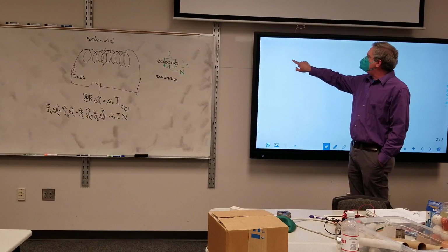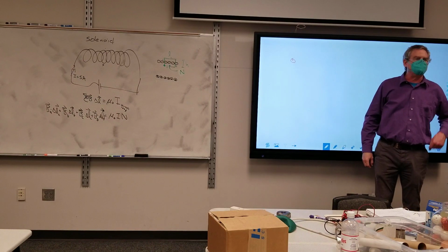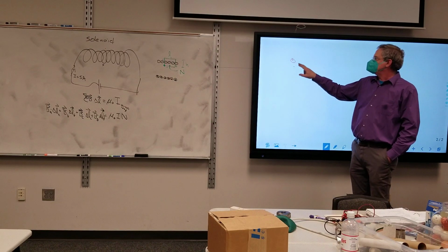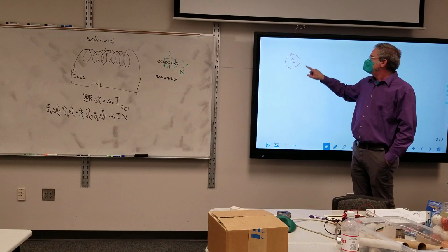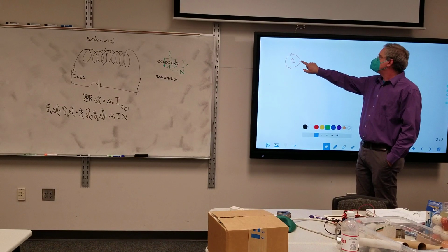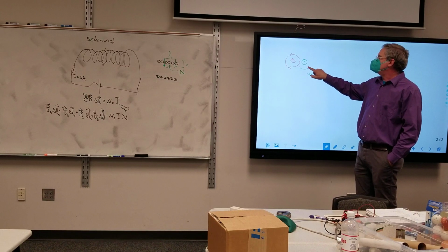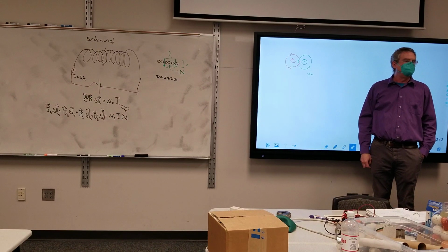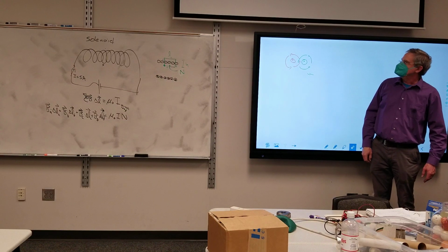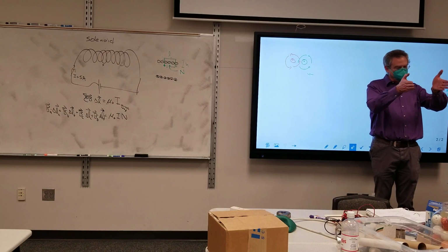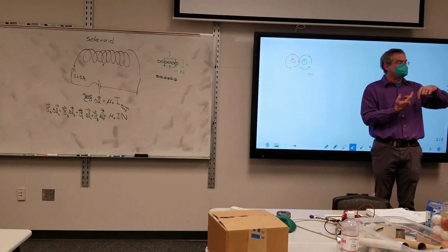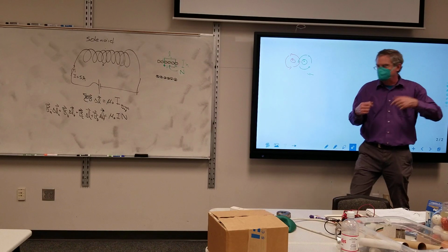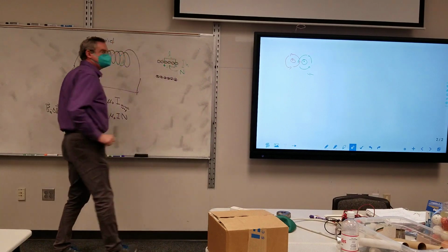So if we look at those wires, if I got a wire with the current flowing out like that, which way is the magnetic field going to be created? Okay, so I got a magnetic field going like that. Let's put a wire right next to it, and it's going to be going in the same counterclockwise direction. So what can you tell me about the magnetic field in between them? They're opposite directions, so they're going to attract. That's not, I'm not talking about the attraction of the wires, just talking about the magnetic field. They're opposite directions, so what happens to the magnetic field? Cancels out. Yeah. So the magnetic field along this path and this path are close enough to 0.